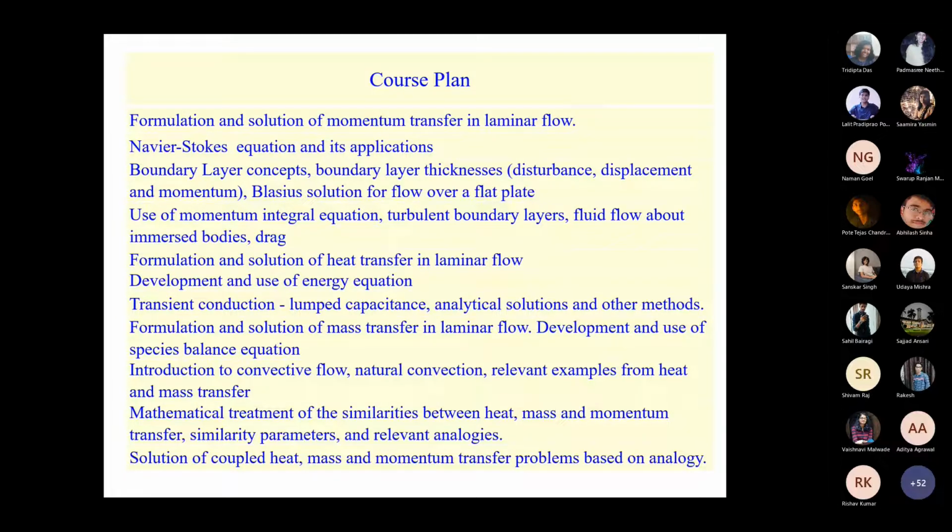And once the lumped capacitance model is valid, probably you'll also remember that it becomes an RC circuit. Then, instead of a PDE, you get an ODE in time, and you would be able to solve for temperature. But there are situations in which the Biot number may not be less than 0.1. So there are analytical solutions, numerical solutions, and graphical representations of results which are also common for transient conduction. We will see a part of that very quickly, but I will assume that it has already been covered by the heat transfer course.